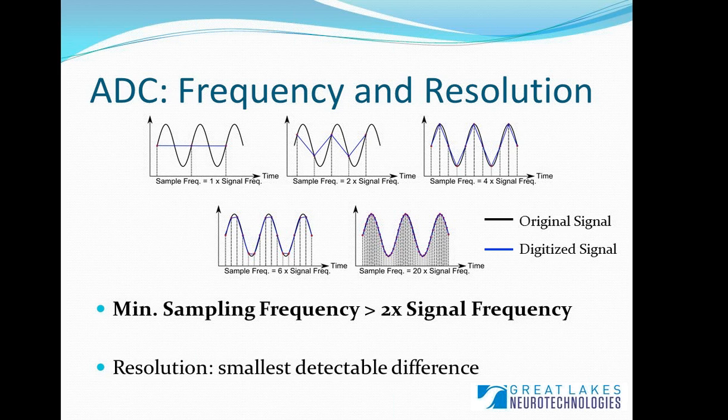If your resolution increases beyond the level of your noise in the system, you'll be resolving noise and you'll be using extra bits of data that won't actually be giving you real information and just be noise. Increased resolution does come at a higher computation cost as well because you are generating more data. However, your resolution increases by a factor of 2 for each bit of resolution added. So 13-bit resolution A to D is twice the resolution of a 12-bit A to D.